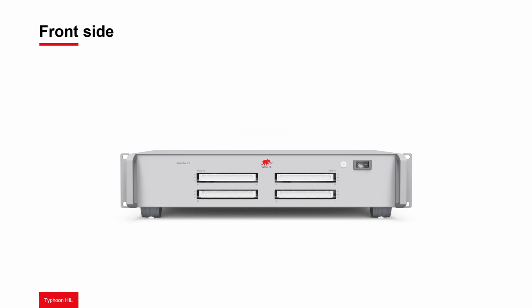On the front plate, we see two rows of connectors. It is important to note that these two rows are independent from one another, as the Remote I/O device is comprised of two independent Remote I/O cards. Each card has 32 analog and 32 digital outputs, as well as 32 digital and 16 analog inputs.